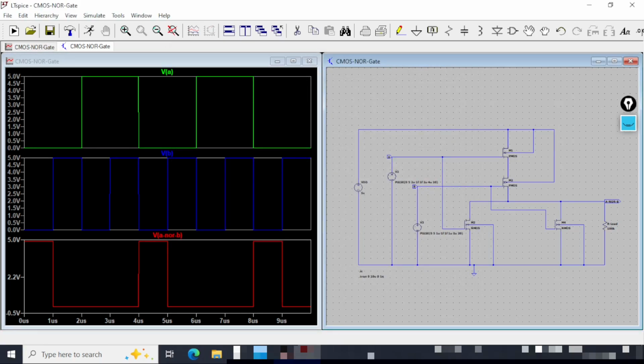So we have done the construction of the CMOS circuit here using the monolithic MOSFETs, the CMOS structure, that is complementary MOS structure, where we have kept double the area for the PMOS with respect to the NMOS, and we encountered one typo error which we rectified through the SPICE deck, which was not visible in the schematic. It only became visible when we scrutinized the SPICE deck. So this is the importance of scrutinization, checking thoroughly before the actual simulation. Otherwise, you have to come back and do a lot of iteration to find the error. We're done for today.